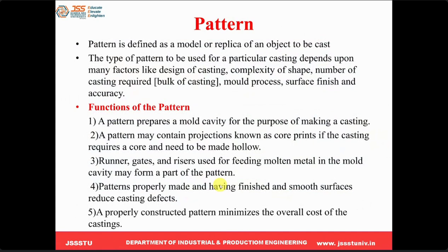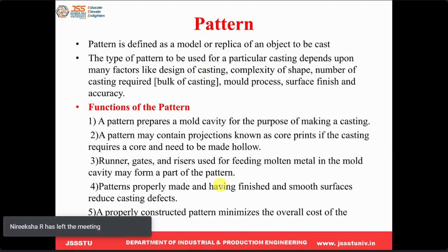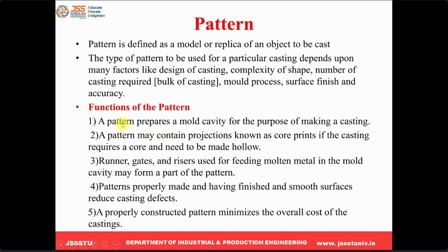Okay, let's come to the next. Now we'll go deeper inside. Pattern. Basically a pattern is a replica of the actual product we want. The function of the pattern is to prepare a mold cavity for the purpose of making a casting. A pattern may contain projections known as core prints if the casting is required to be hollow.